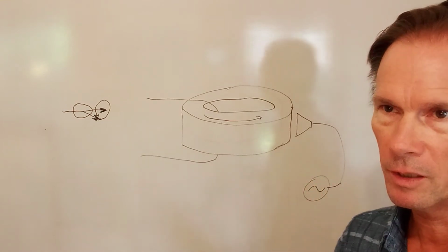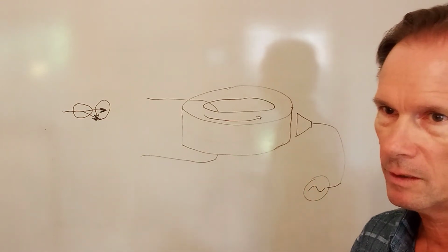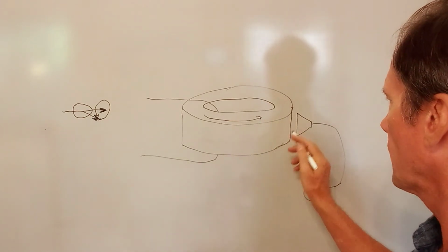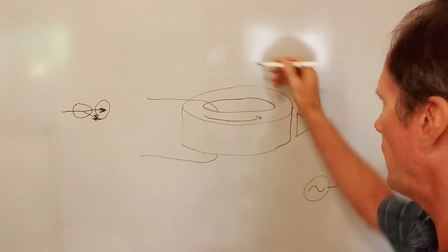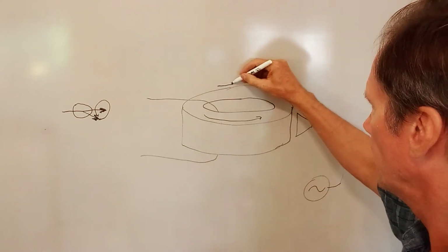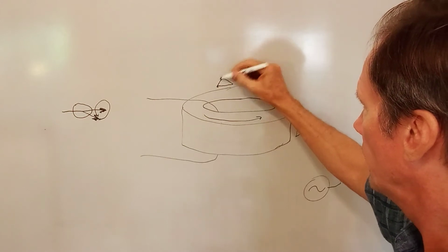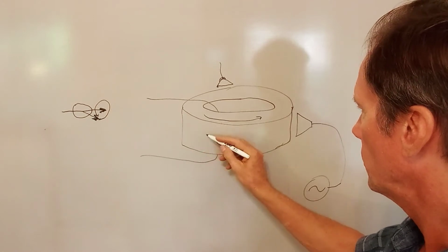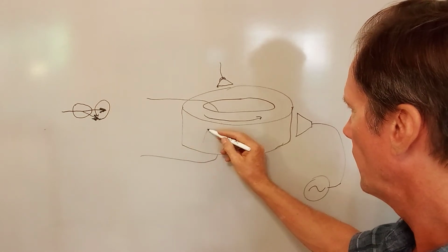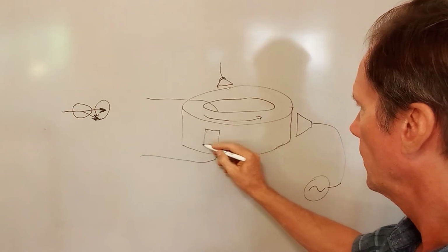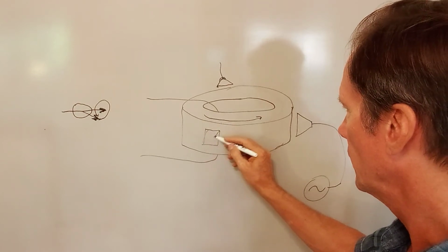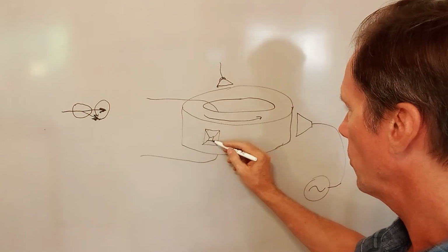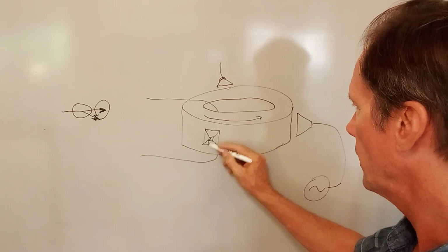To see the most measurable effect of the suggested experiment I'm making, you would possibly need to stimulate this toroid with 3 different microwave sources on 3 different sides, with some type of microwave antenna, maybe a rectangular, square, or circular horn antenna hooked to a generator.